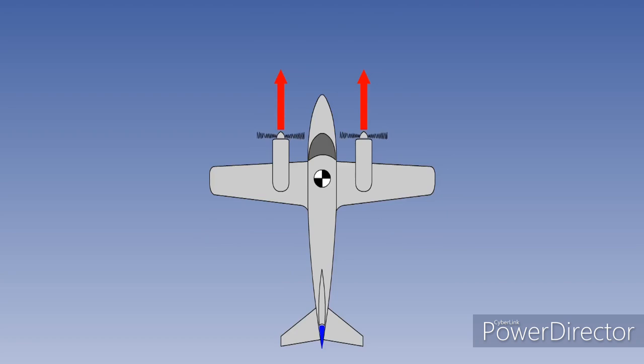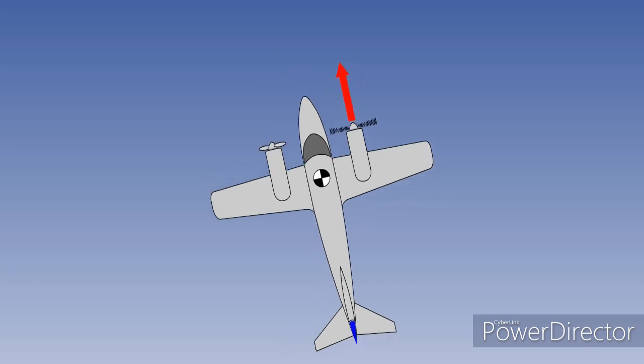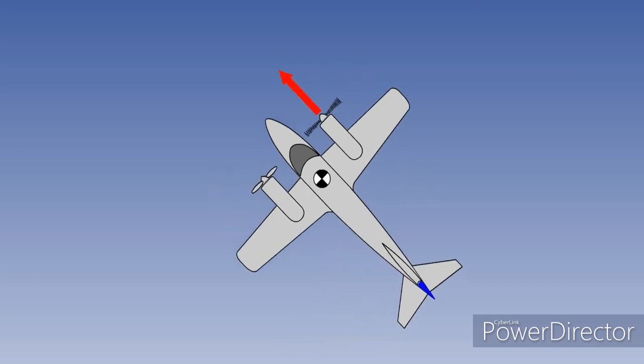The first use of the rudder we will look at, and perhaps the most important, is to give the pilot the ability to maintain directional control in the event of an engine failure on a multi-engined aeroplane. A propeller-driven aeroplane is illustrated, but the same would be true if it was powered by gas turbines. The left engine fails and a left yawing moment is generated.